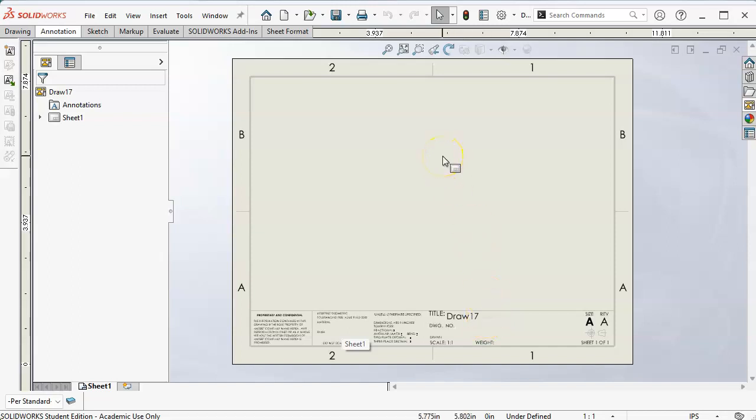And then I also want to do this as a multi-sheet. So we did the singles, and we could just keep on going doing single parts. With the configured piece, it goes a little bit different. But if you drew the quad or the single 30 by 30 all the way up through the 120 by 120, save as and open, and have those, whatever it works out to, 8 or 9 files, then you create a drawing for each one, or you create a multi-sheet drawing for the item.